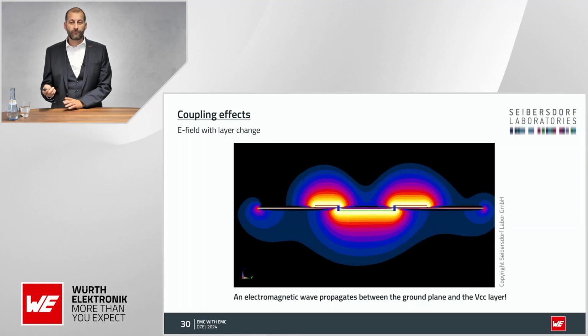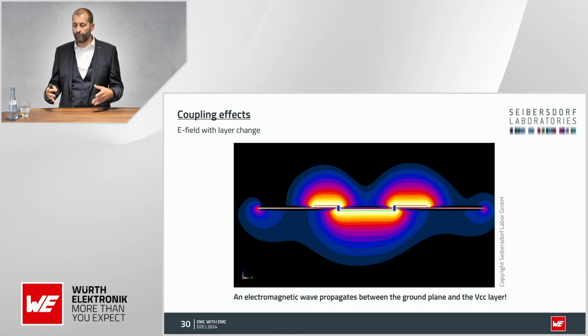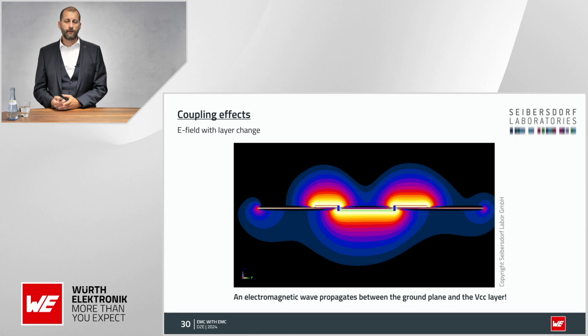So, of course, we cannot avoid vias. I mean, we can certainly not avoid it with 2 layers, nor 4 layers, nor 6 layers. But what we can do is, if we have a signal that's traveling really fast on a transmission line, we should avoid vias at all costs. And then we go to the analog part or the slower digital circuitry and place them there if needed, and only if they are needed.